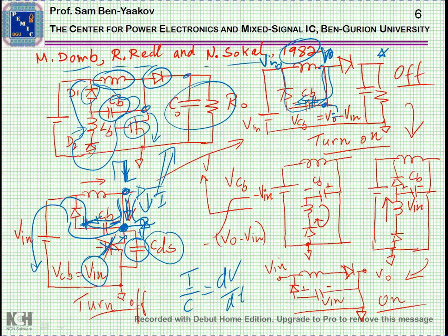Vout is higher than Vin, to this magnitude. And this is during the off time, in terms of the transistor. The transistor is off, current is flowing through the inductor and diode, and consequently we are in the off state, powering state.